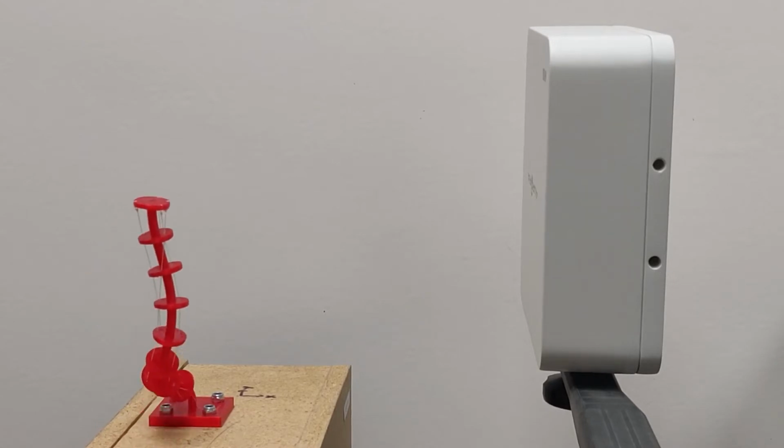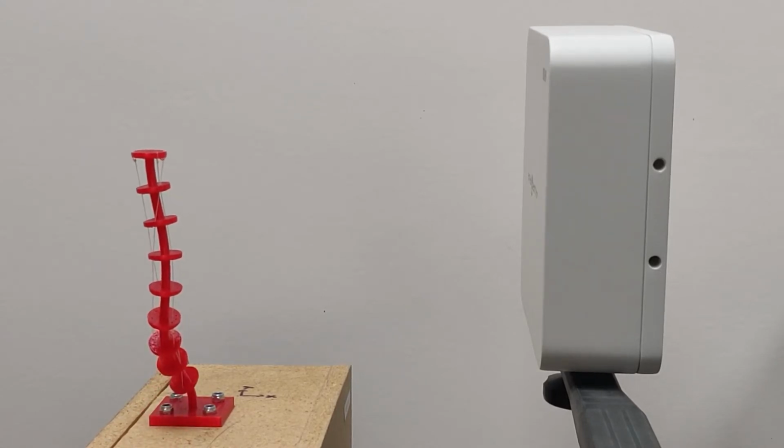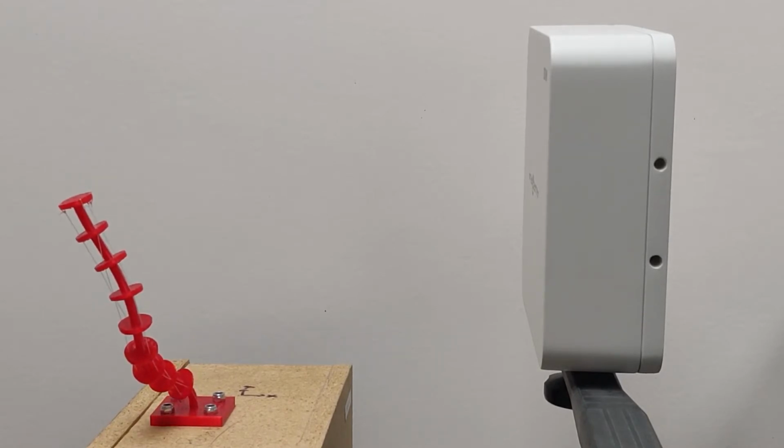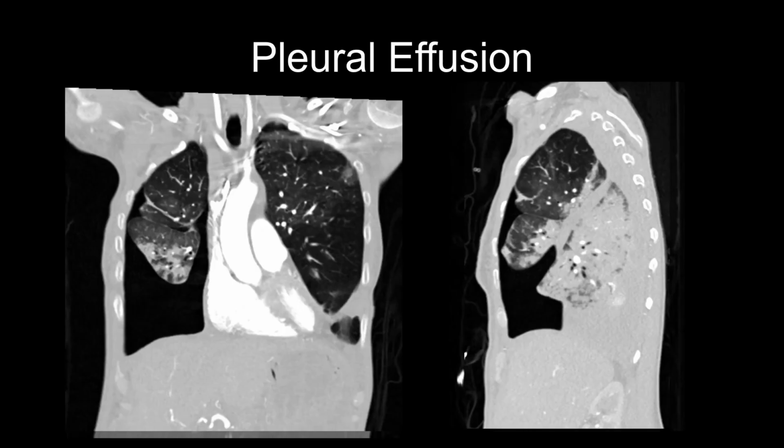With non-straight routings, we can achieve interesting shapes, as seen here. However, kinematic modeling is computationally expensive. Tendon-driven robots may potentially improve minimally invasive surgeries, from their ability to curve around anatomical regions and access difficult-to-reach sites. Their flexibility adds inherent compliance, which improves safety near these sensitive anatomies.